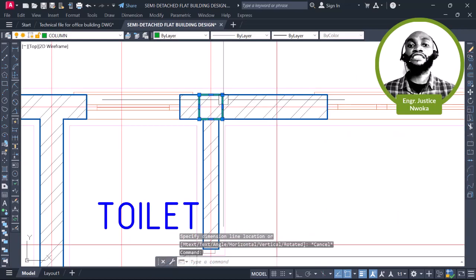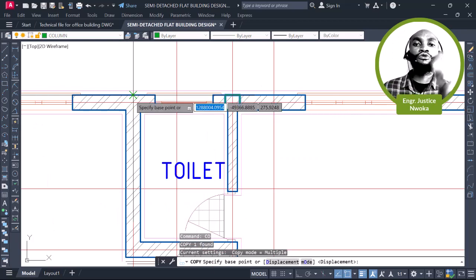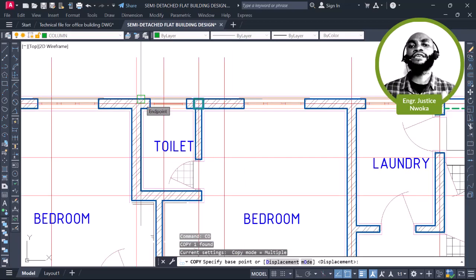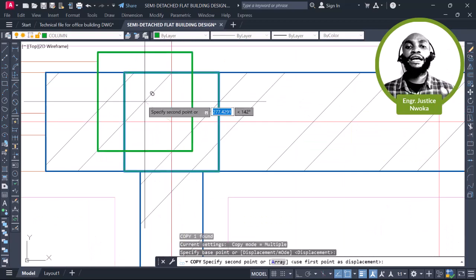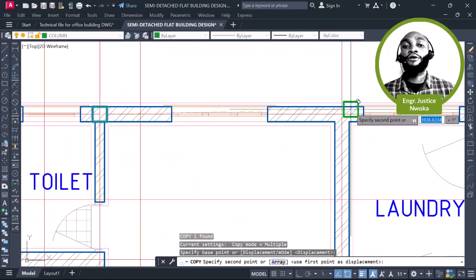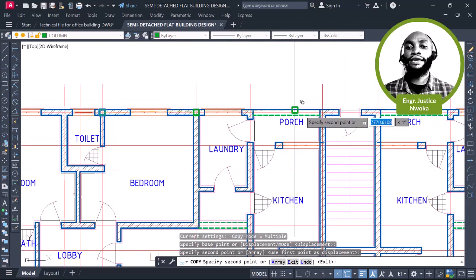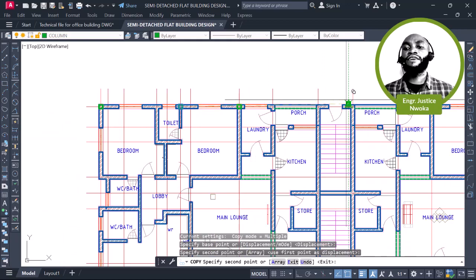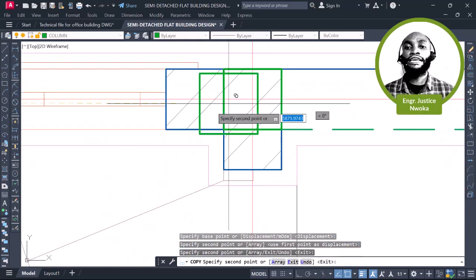That's fine. Let's just continue first. If there is need for us to put the column here, we'll do that. Now I see that we are designing this building live with you. So if you have any reason that this column should be here, I would like you to drop it in the comment section and we will do that. Then we will come here and click on this place here, and put a column here. Now you have to place your columns first, and after that we will check if they are more than 6 meters. So just place your column right now.